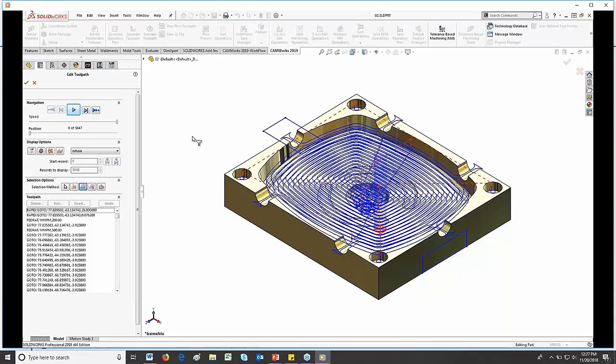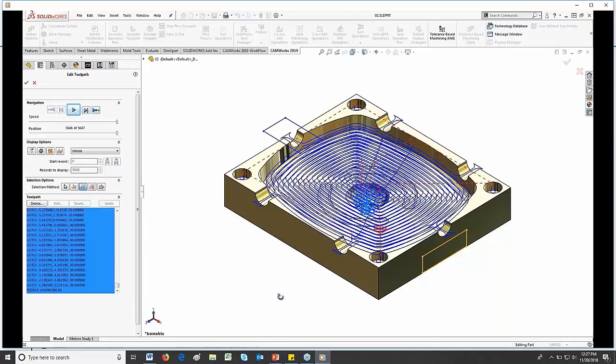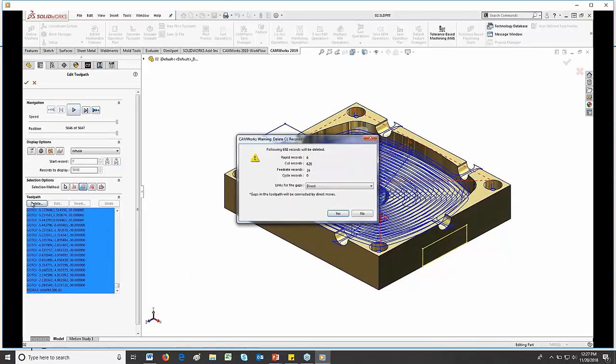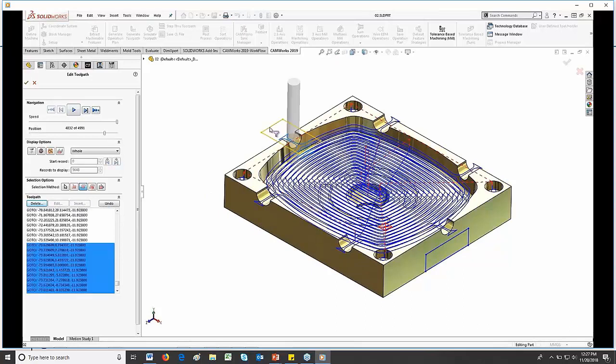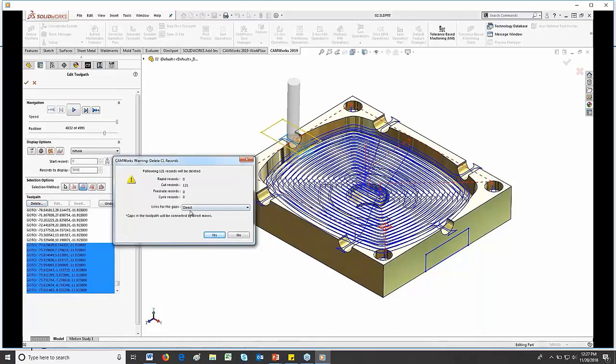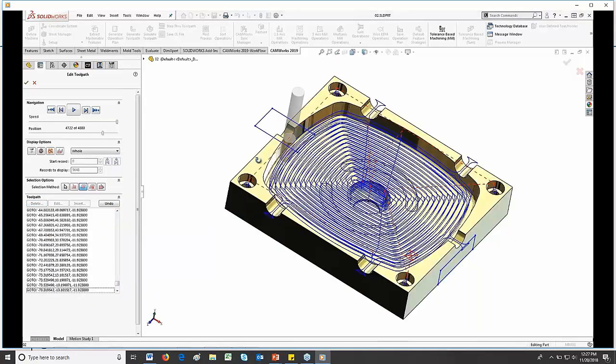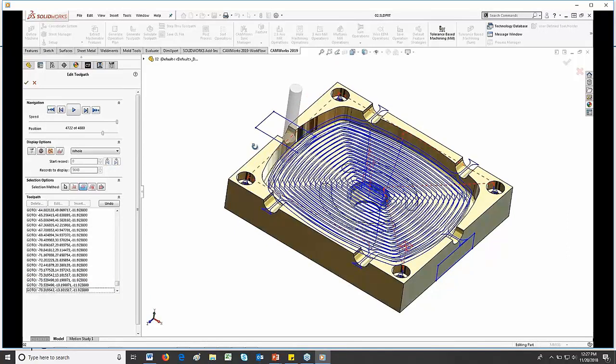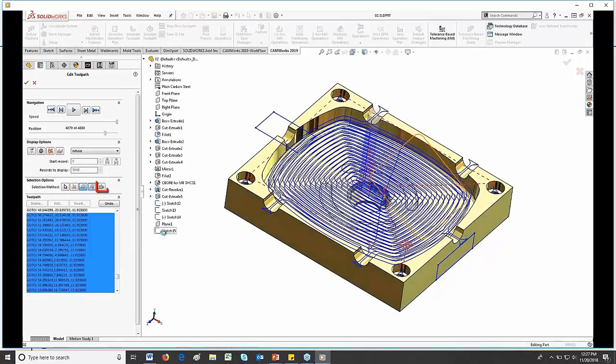There's a sketch up at the top of the part there that's sort of like a clamp, and then one down below if you want to cut the toolpath off at a specific Z level, for example. So there's just a lot of new editing capabilities that have been added here, and different ways of being able to select things, trying to make it easier for you to create exactly the type of toolpath that you want to create. Okay.